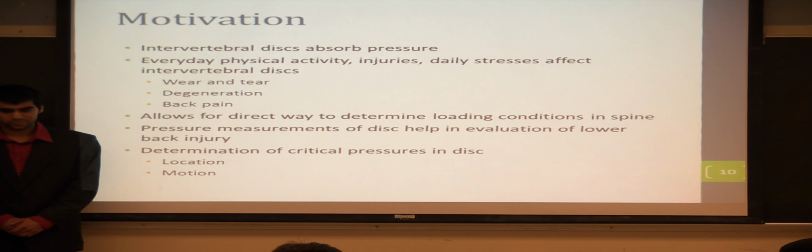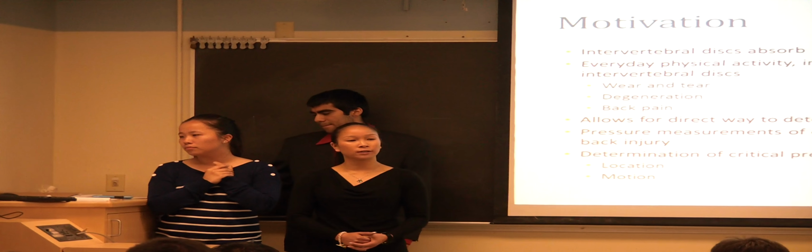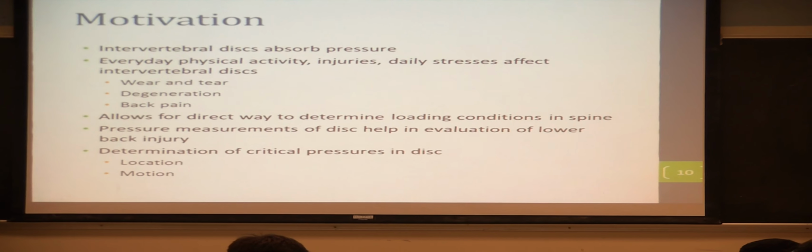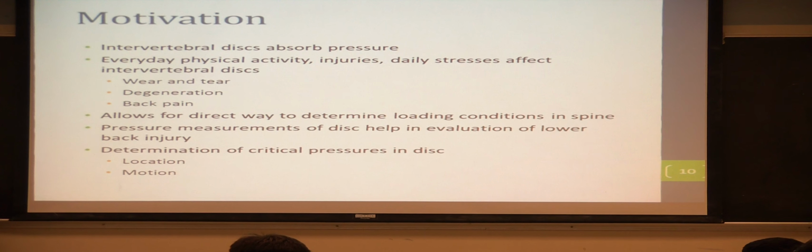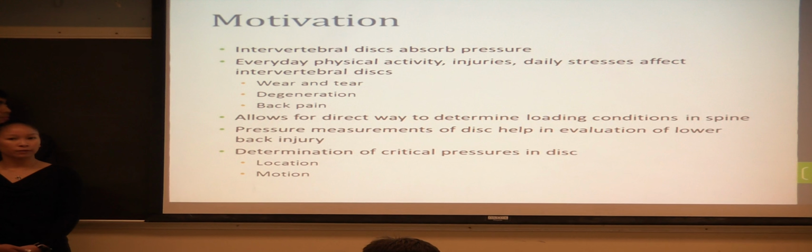So why is the needle pressure transducer so useful? Well, in the biomedical field, it's important to know stresses, strains, and pressures which the body experiences. This type of information is especially critical in designing durable prosthetics. So the needle pressure transducer can be used to measure pressure in joint surfaces. For example, in the intervertebral discs. Intervertebral discs lie adjacent between vertebrae in the spine, and they separate vertebrae from one another.